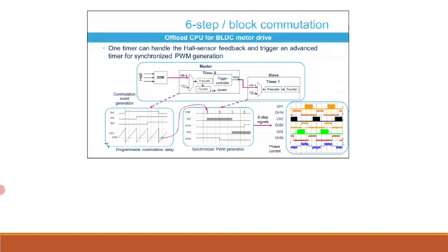The capture register 1 holds the timing interval between successive Hall sensor edges and is necessary for the speed regulation loop. The compare match event is propagated to the slave timer through the TRGO output. These events serve as communication events and trigger changes for PWM generation.